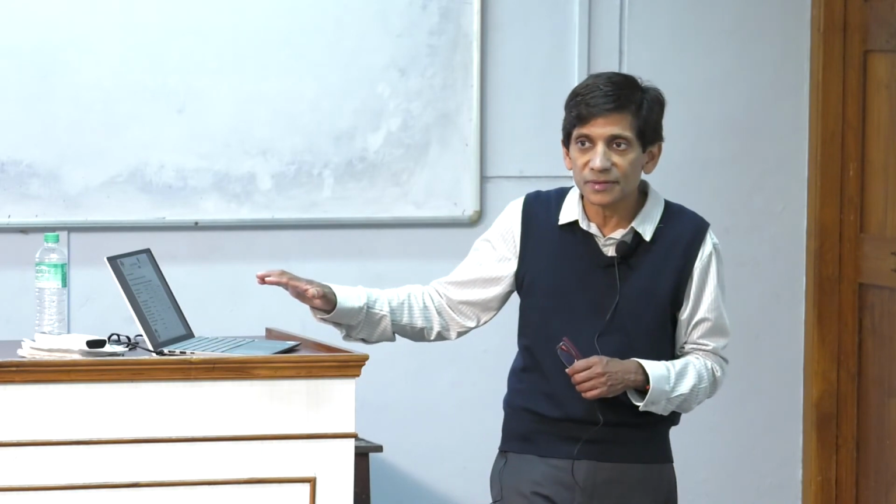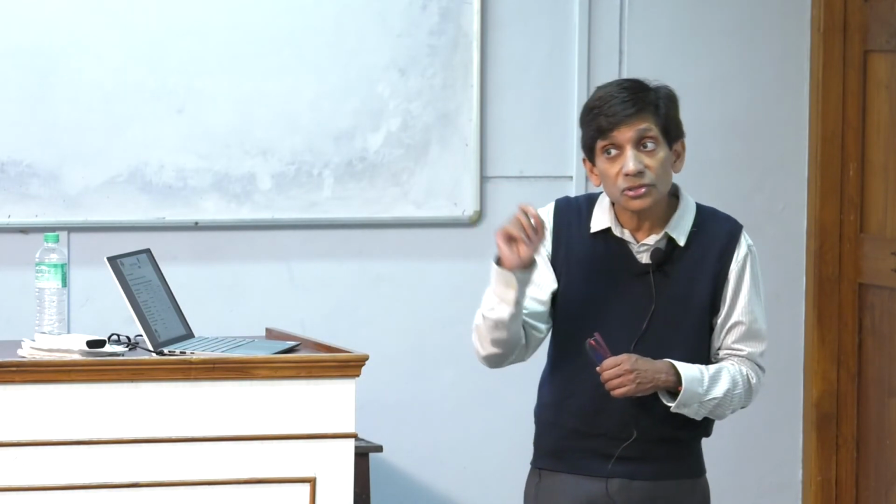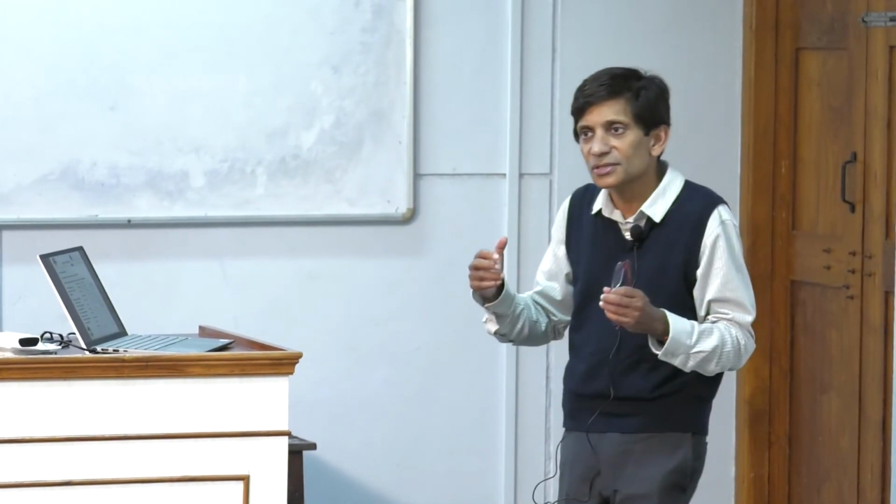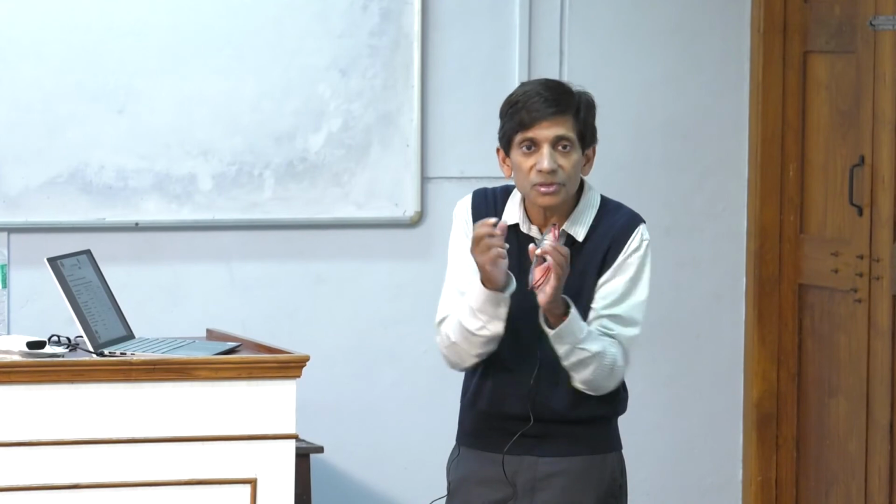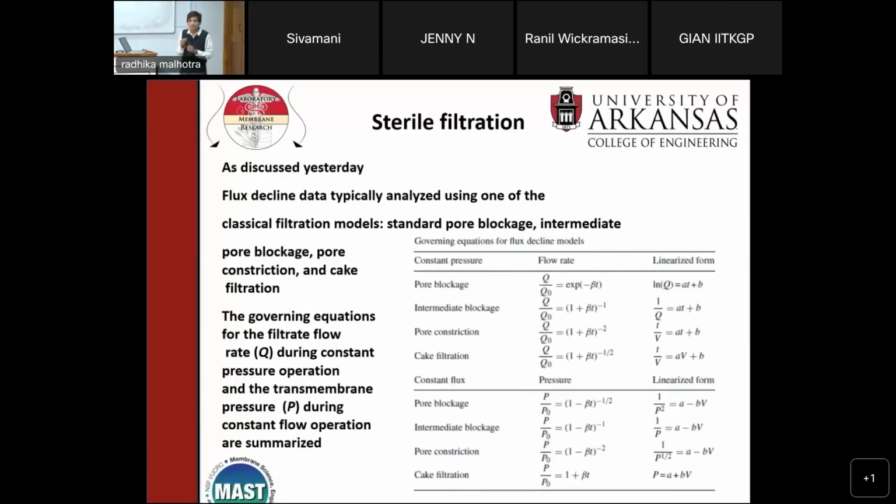It works very well actually for sterile filtration. This is a case where it works very well. But remember, sterile filters are also not track-etched membranes. They are typically going to be phase inversion or something else, so that you have a lot of interpore connectivity, because that maximizes capacity. What's important here is capacity. Capacity means how much you can process before your flux is too low and you have to abandon it.